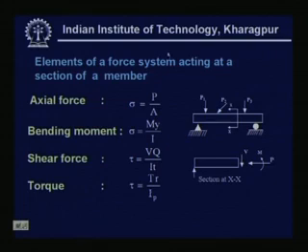Please note that T is the thickness, what we considered there as B, also the width of the section. Same thing here, it has been written as T. Although this particular beam acted upon by loads P1, P2, P3 etc. does not have any torsion acting on it, we have still written down the equation for the torque, which gives the shear stress as Tr by Ip.